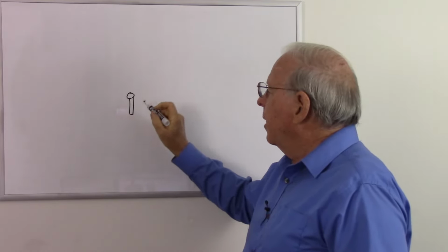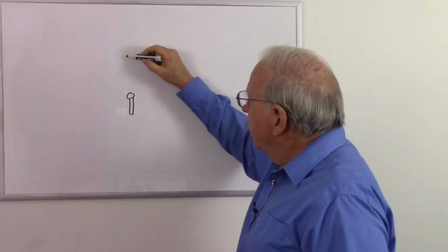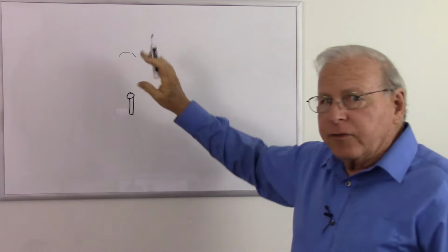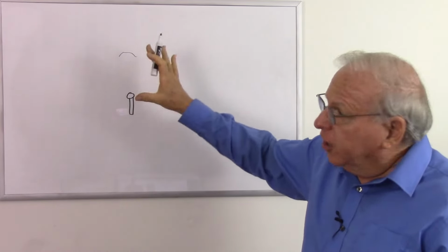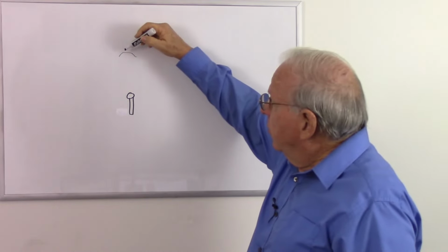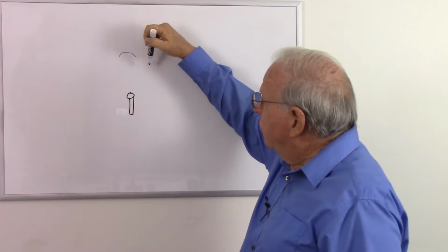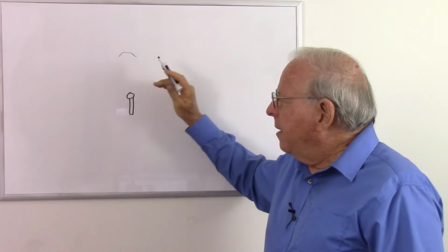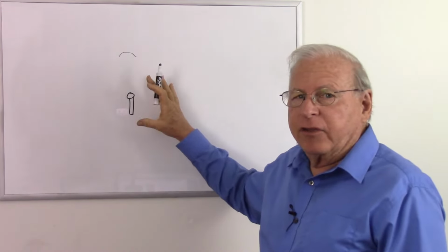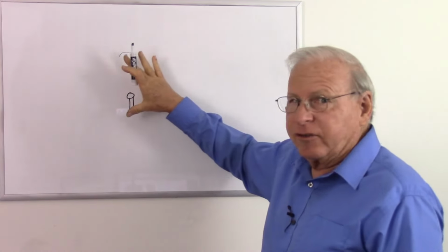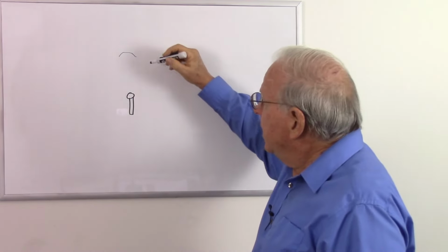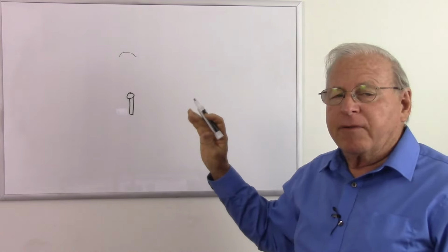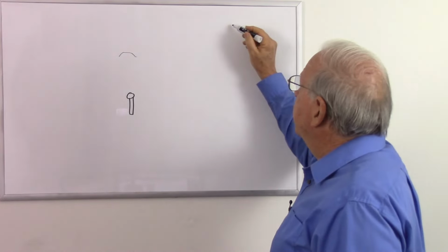So inside the chamber we'll put a microphone in the middle, just draw it like a little lollipop there, and we'll have something like a loudspeaker some distance from it in a particular direction. And what we're going to do is adjust the sound probably to some average power, or maybe even the peak power the microphone can accept. I've never done such a test. I just have a good idea of how it's done. But we're going to set it at a certain power, and we're going to make that our reference, and so we will call that 0 dB.